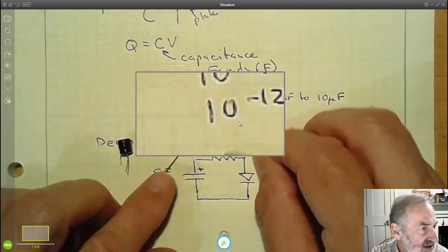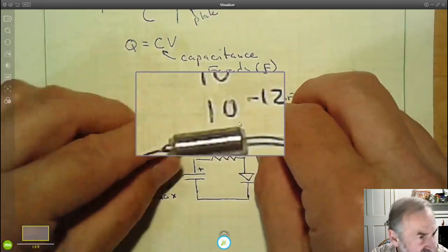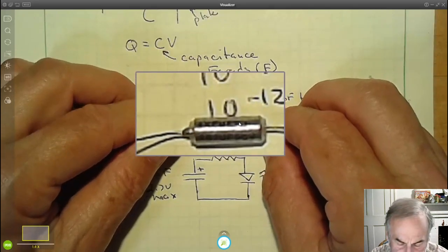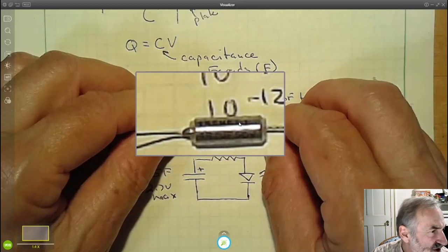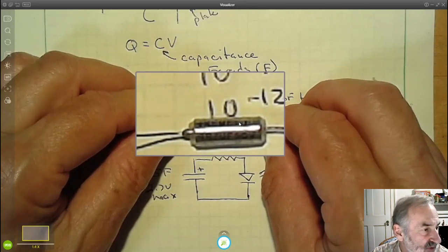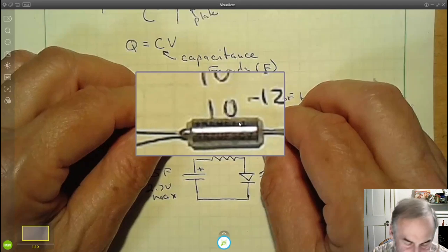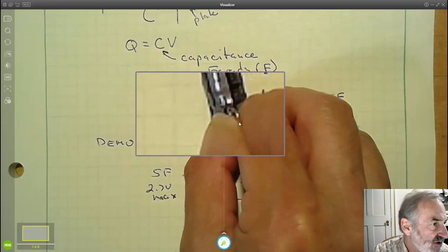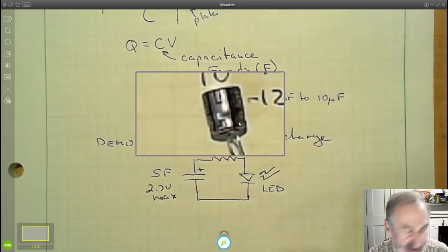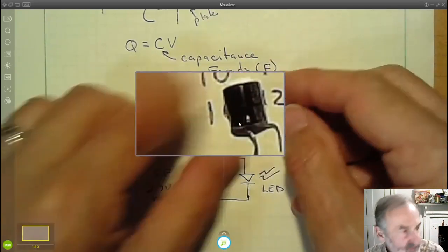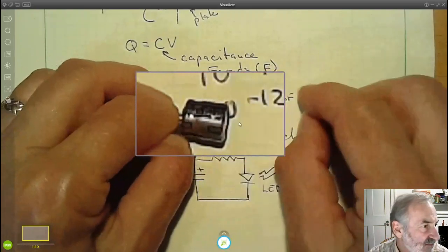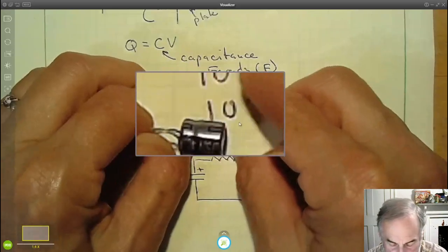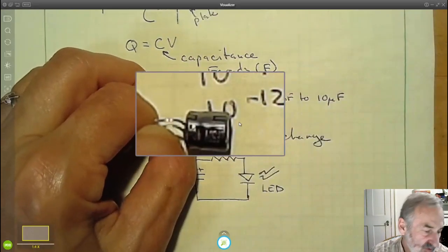And then finally, this is a capacitor, a type called tantalum. Well, you can barely read it. It's 4R7UF. That means 4.7 microfarads, and it says 50 volts. This is another electrolytic capacitor. This is a smaller value. Once again, there's an arrow pointing to the negative side, and I don't know that we're going to be able to read it, but it's plainly marked. Well, it's plainly marked if we had better eyes, with its value right on the side.